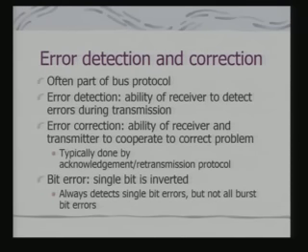What kind of errors can occur? The simplest error is bit errors. Okay. So, here a single bit is effectively inverted. So, when we try to detect a single bit error, we can detect single bit errors, but not all burst bit errors can always be detected.